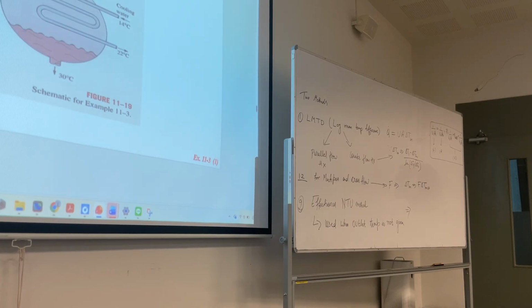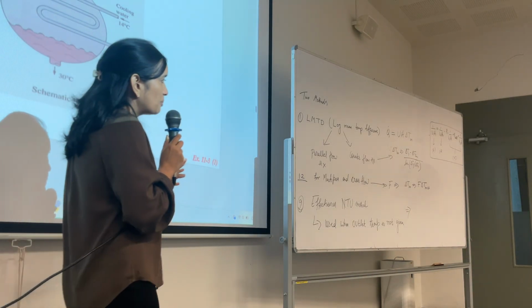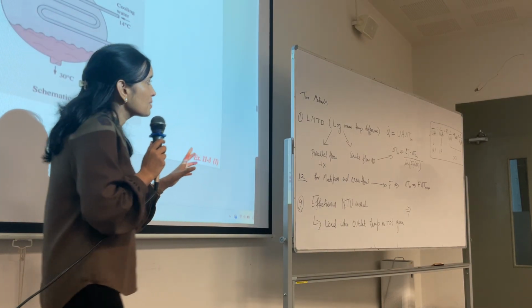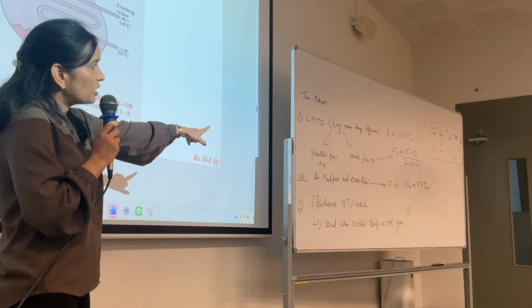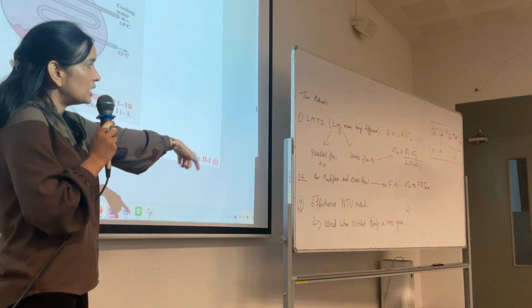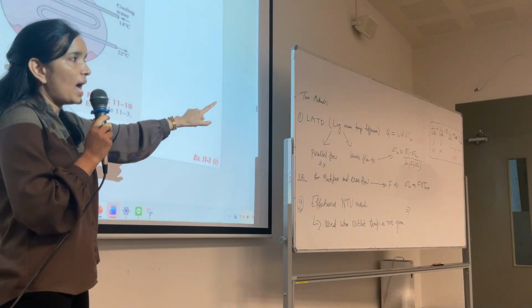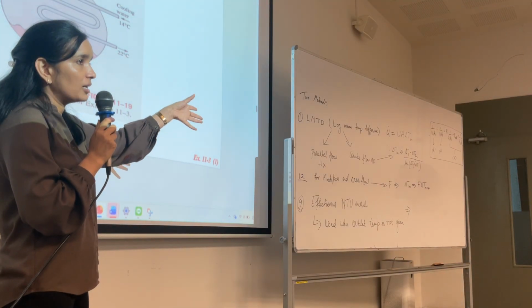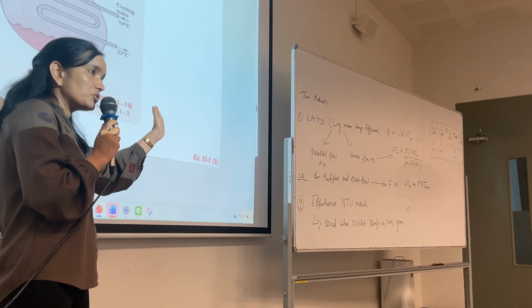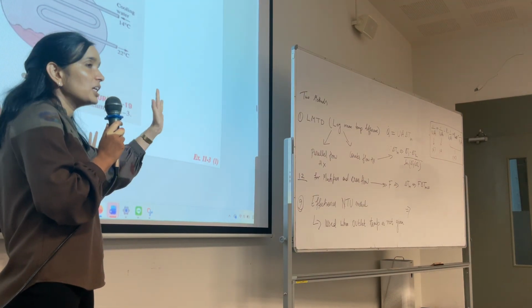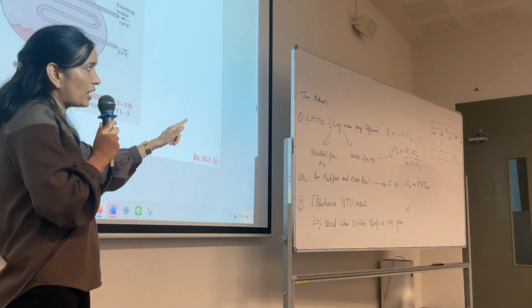Analysis of a heat exchanger is done by two methods. First is LMTD, second is effectiveness NTU. For LMTD you use that formula for parallel flow and counter flow. If it's multi-pass and cross flow, you have to add F, which is the correction factor. The value of F is given in the graph. I will explain how to find the value of F from the graph.